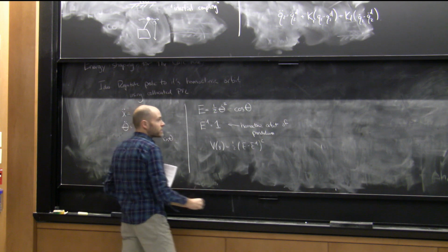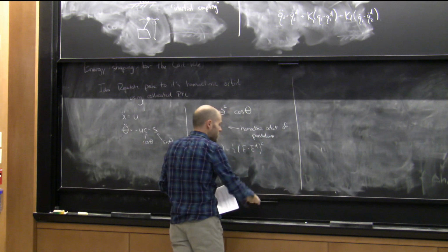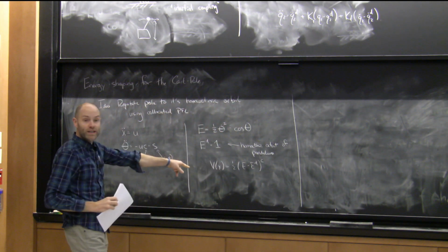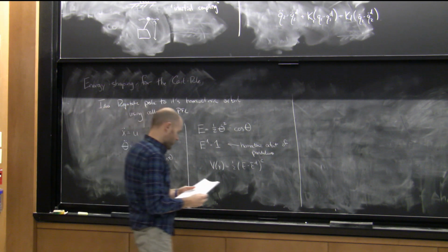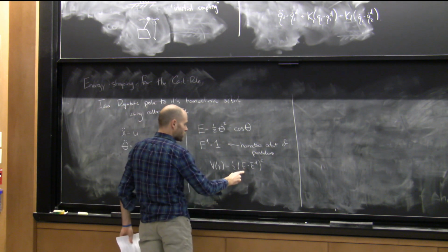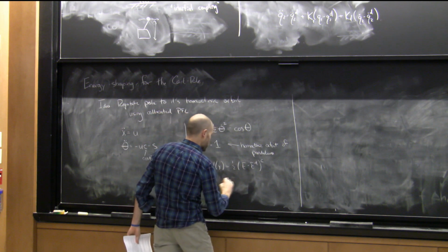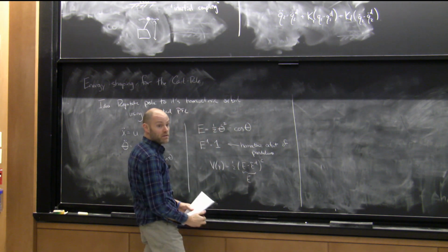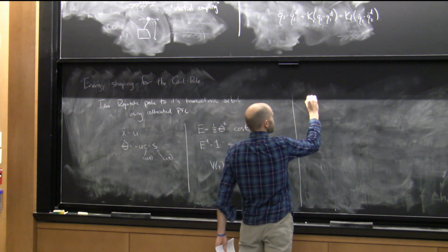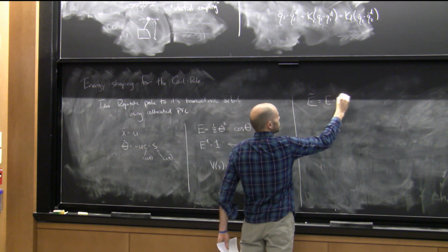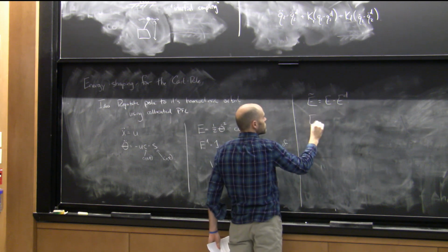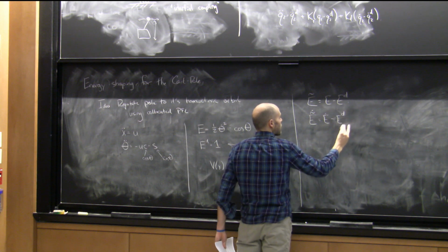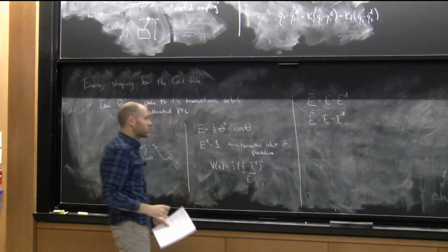Okay. And the way we're going to do that is with our old school nonlinear control hats on. We're going to write the terms down, we're going to manipulate some equations, and make sure that that thing's going downhill. Okay? So the dominant term here is E, so if I call this thing E tilde, then I'd like to know what E tilde dot is looking like. How is my error in energy going down over time?